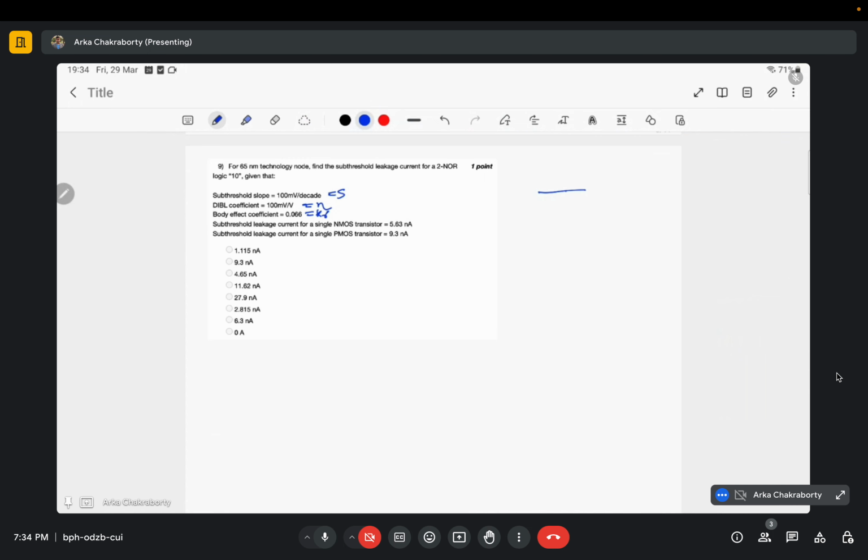It is a NOR gate, right? So PMOS stack, input is 1 0, and this is my output stack. One zero. So my output will be 0 because it will discharge, and the charging part is not present. So output will be 0, and it discharges through this path. So this is off, this is on, this is off, this is on.